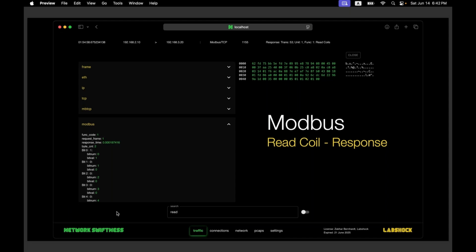If you are connecting these legacy systems into the new world, for example into the cloud or whatever, and someone has access here, it is a very big problem. You need to think about segmentation and about how to maybe replace Modbus or somehow secure it.